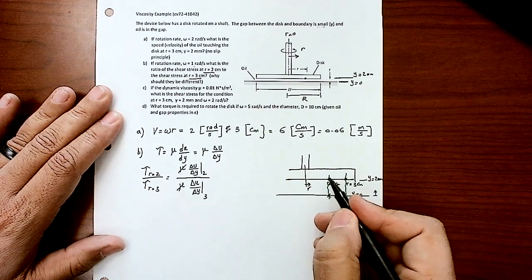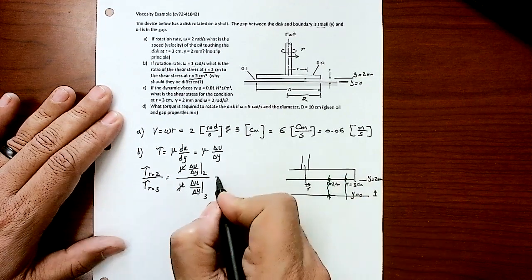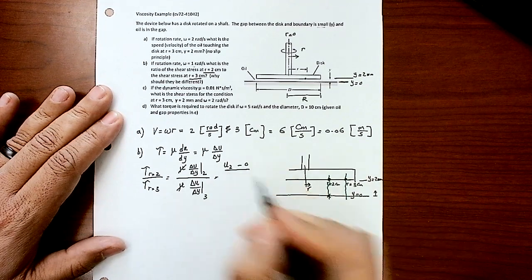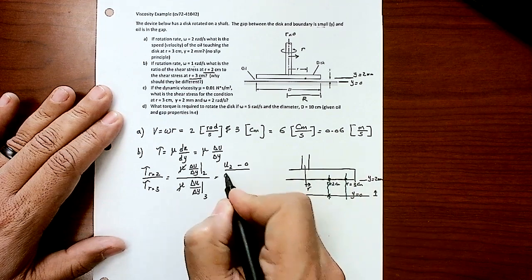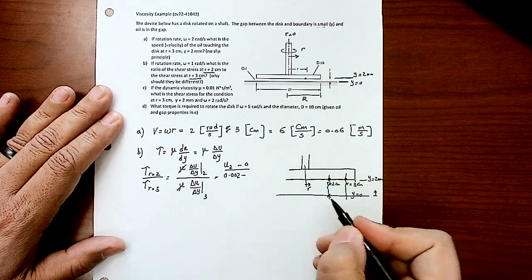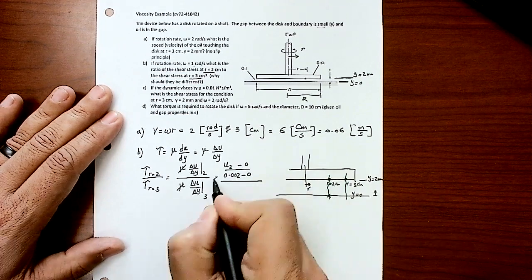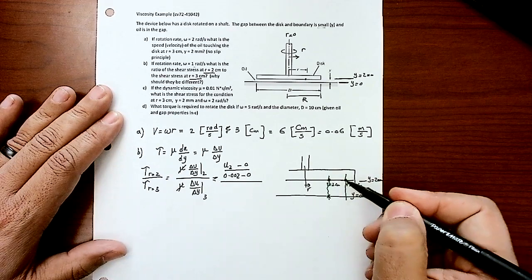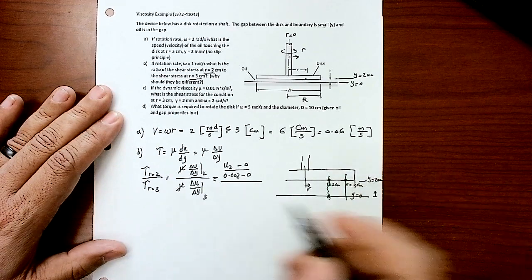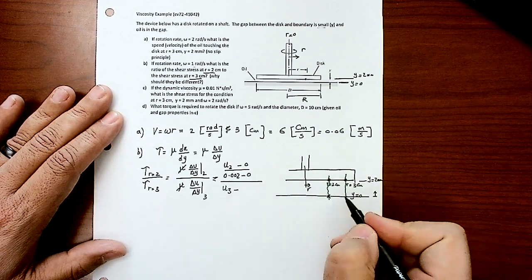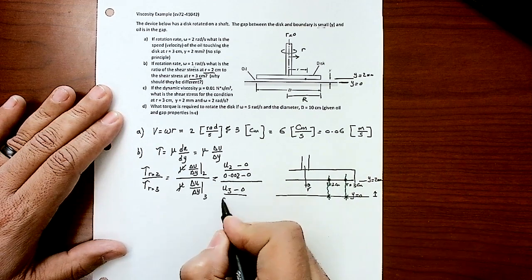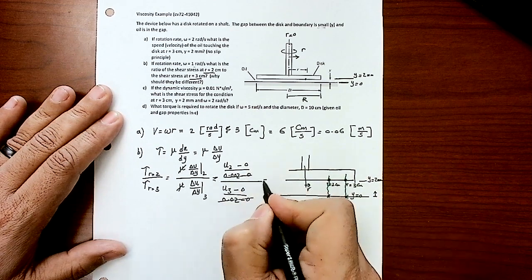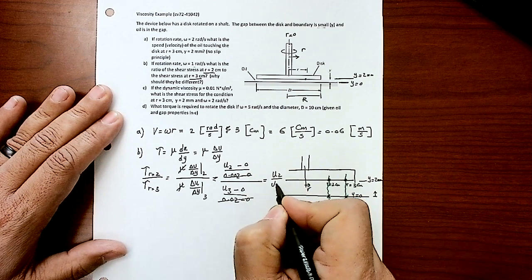So delta u over delta y at the 2 centimeters, I'm going to pick this point and this point, right? So it's u minus u divided by y minus y. So the velocity at 2 minus, we know the velocity here is 0, divided by y of this point, which is 2 millimeter, I'm going to make that 0.002, minus y of this point, which is 0. Then you divide that by the delta u by delta y at this location, u minus u divided by y minus y. So it's u at 3 minus the velocity here, which is 0, over 0.02 again. This is y of this point minus 0. This will cancel out. So it's going to end up to be u2 over u3.